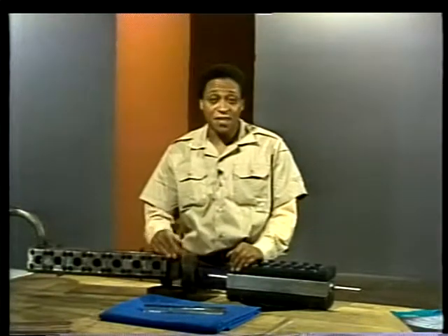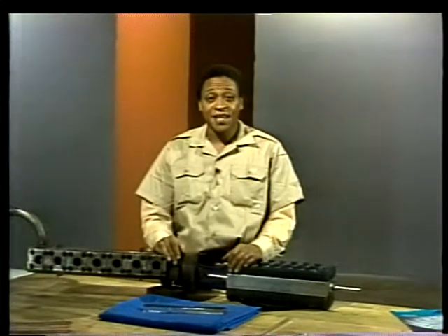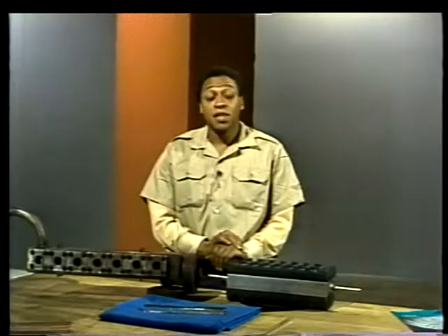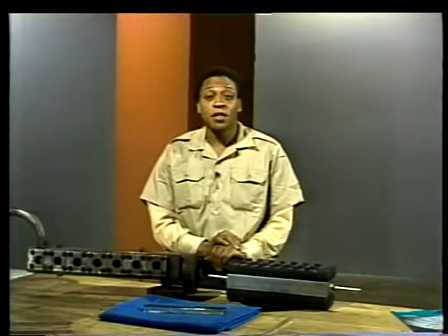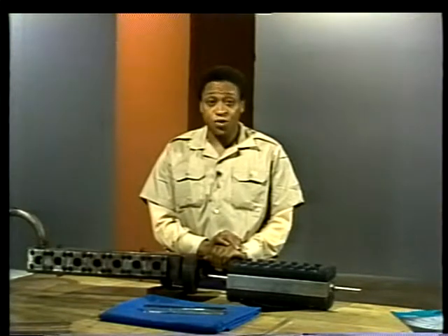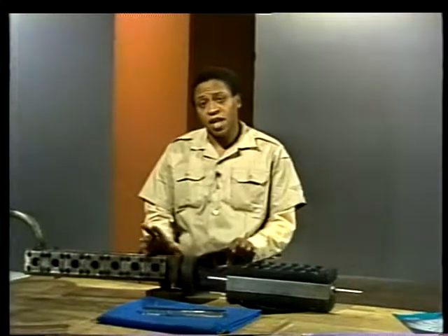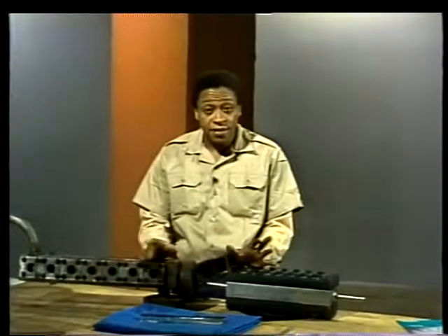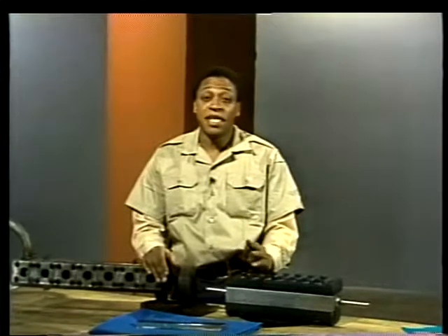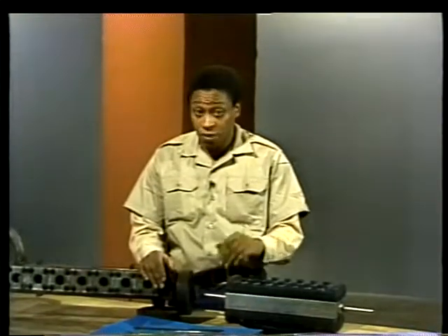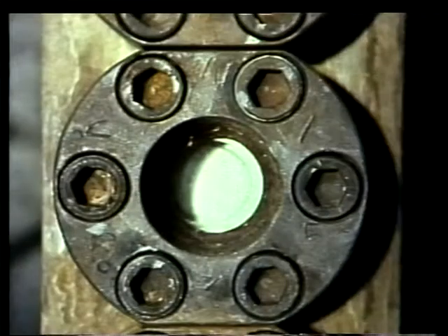Now that we've covered some basic points about gauge glasses, let's talk about some of their potential problems. We'll identify them, tell why each is a problem, discuss their causes, and describe how each is fixed. There are 6 maintenance problems common to gauge glasses: opaque glass, plugged connections, leaks, glass erosion, cracks in the glass, and complete glass failure.